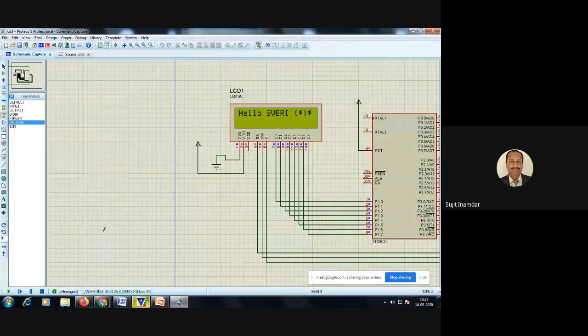So that code also has to have some required code added, so that once the query is ended, the next positions should go blank. But this cursor, if you look at this 16 by 2, this is the second row, it is just going ahead one by one, 16 times, as this is a 16 by 2 LCD display. So what about the additional 5 characters? For that we are supposed to edit the code there.